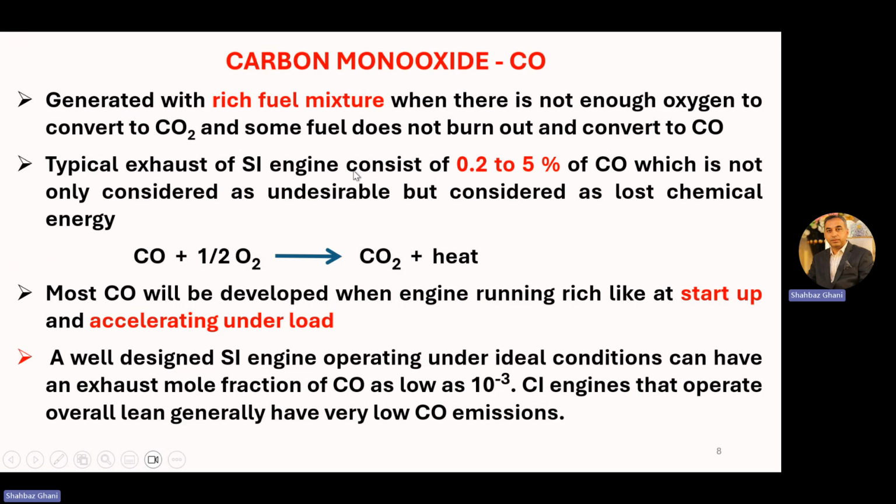Typical exhaust of an SI engine consists of 0.2 to 5% carbon monoxide, which is not only considered undesirable, but considered lost chemical energy. So carbon monoxide plus half a mole of oxygen gives us carbon dioxide plus heat. Most of the carbon monoxide will be developed when the engine is running rich, like at startup and accelerating under load.